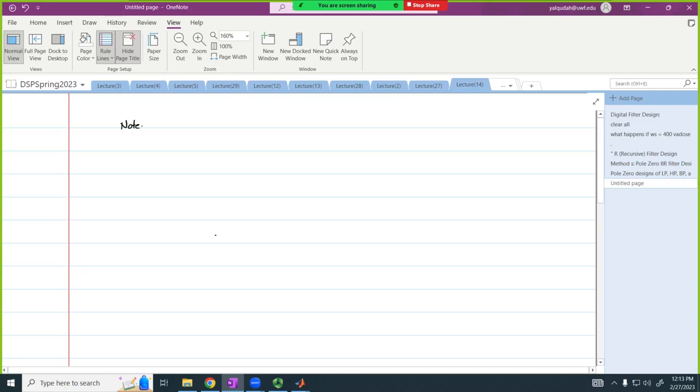And one other thing we can do is place multiple poles and zeros near each other. If we place multiple zeros or poles near each other, that will lead to a flatter frequency response.